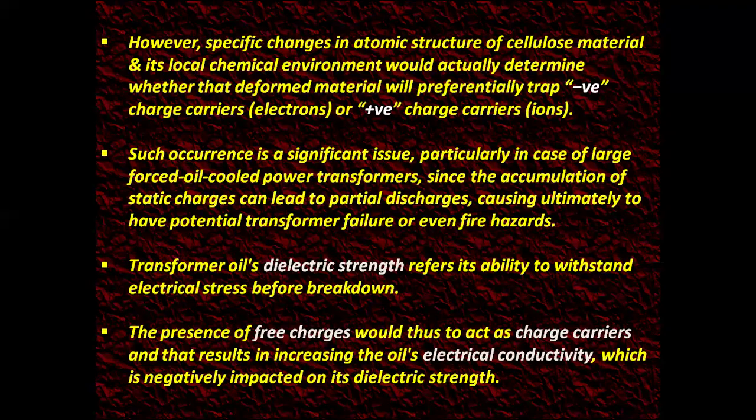Transformer oil's dielectric strength refers to its ability to withstand electrical stress before breakdown. The presence of free charges acts as charge carriers, and that results in increasing the oil's electrical conductivity, which negatively impacts its dielectric strength.